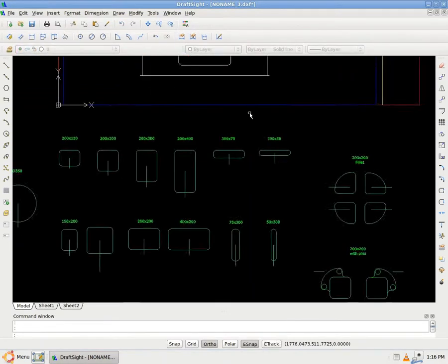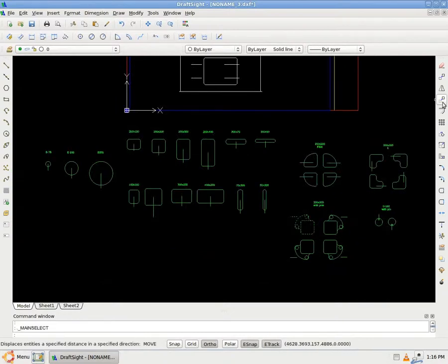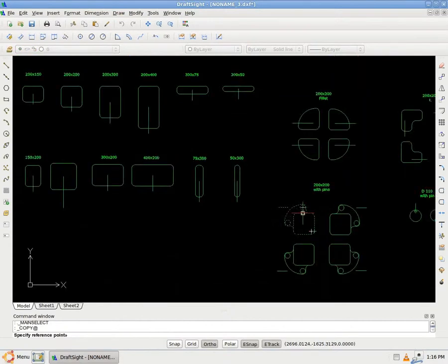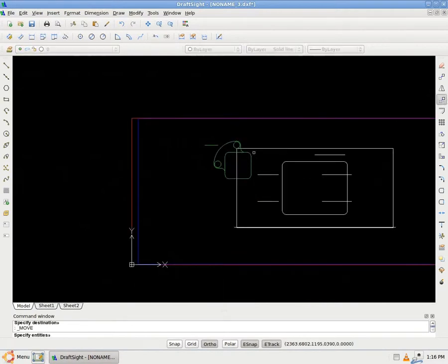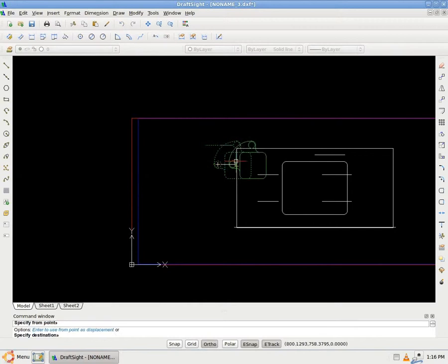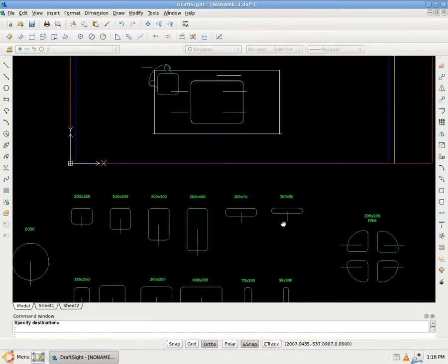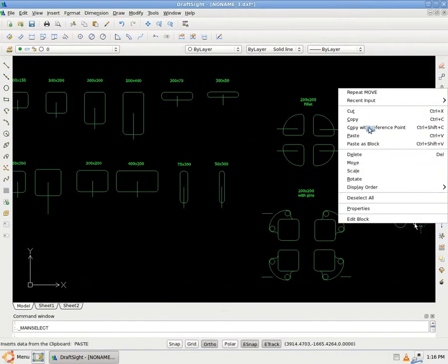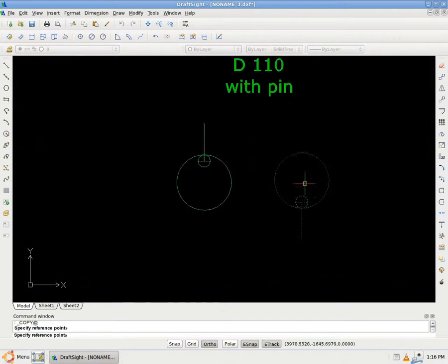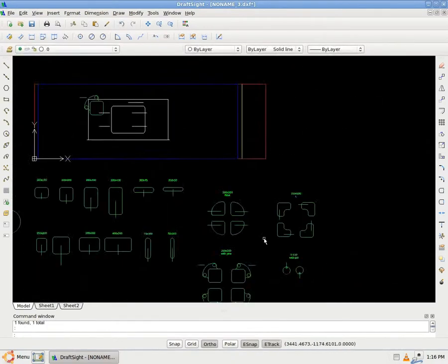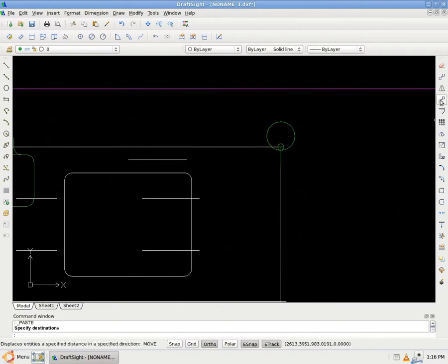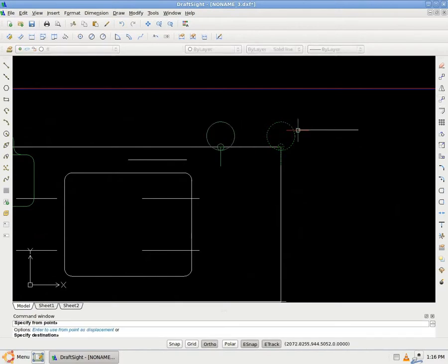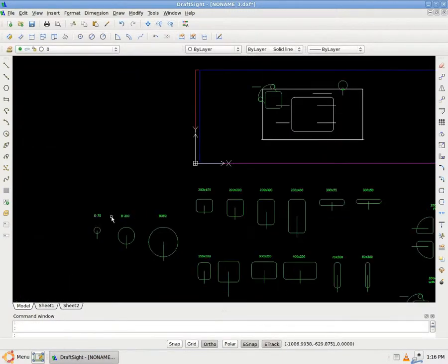My job seems ready, but I still need to place the vacuum cups. I will just get some cups with pins, so that I can place my piece correctly on the table, and then a couple of cups to stop the piece from moving around.